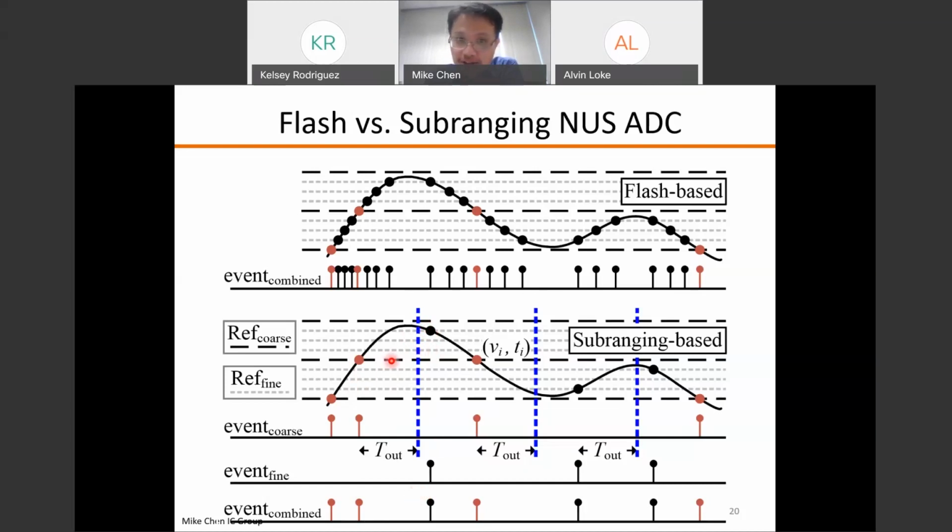They say that for non-uniform sampling, you just need to meet the Nyquist rate of the average sample rate. So that's kind of what we're doing here. We use that to control the average sample rate that we need for the application.